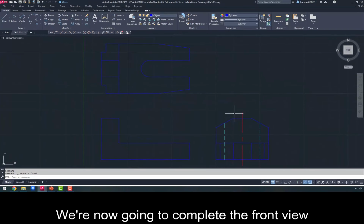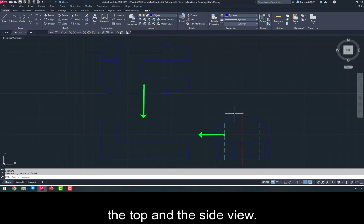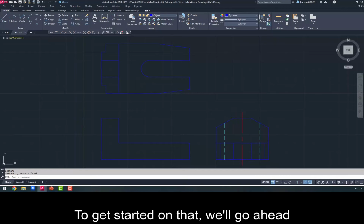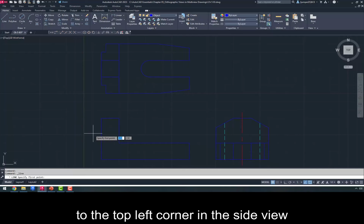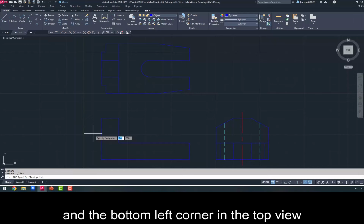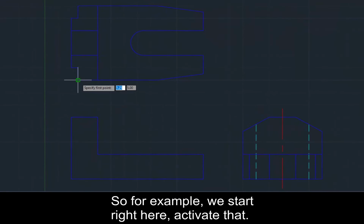We're now going to complete the front view using the information we have from both the top and the side view. To get started on that, we'll go ahead and use the line command. We want to move the cursor to the top left corner in the side view and the bottom left corner in the top view to activate the object tracking option for both corners. So for example, you start right here, activate that, beautiful.